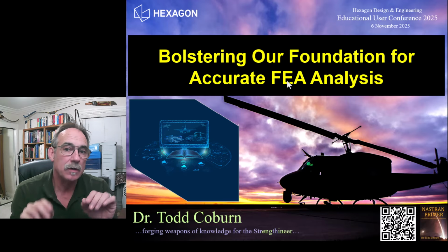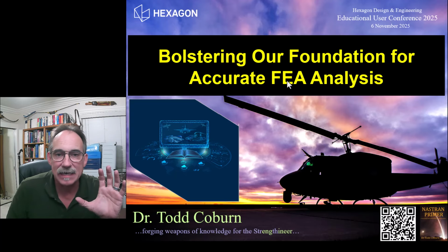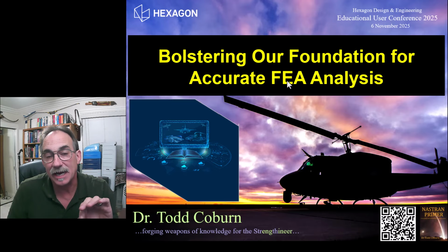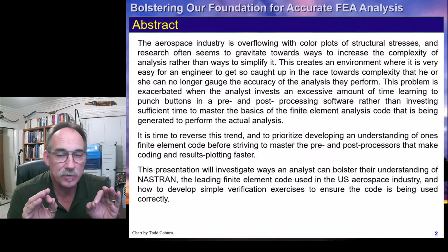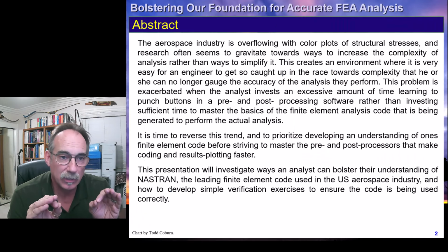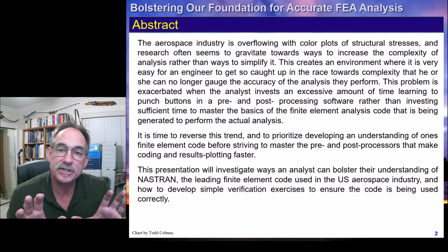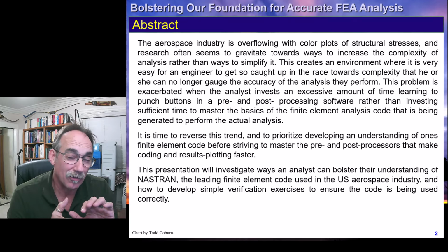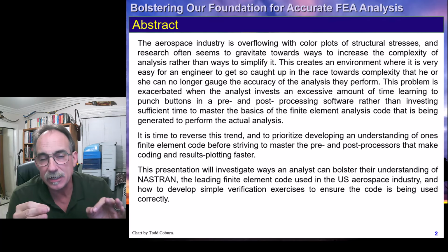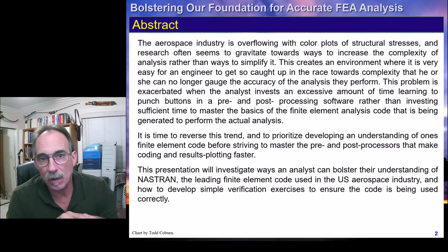In order to counter that, I want to propose some ideas that are kind of dropping down to a more simple model and understanding how NASTRAN and the elements it uses work. So in order to make a good finite element model, not only do we need to be agile in the pre and post processor, we also need to understand the NASTRAN elements, which ones are being created, what are their limitations and idiosyncrasies, and how to leverage that so we get what we need in our model.